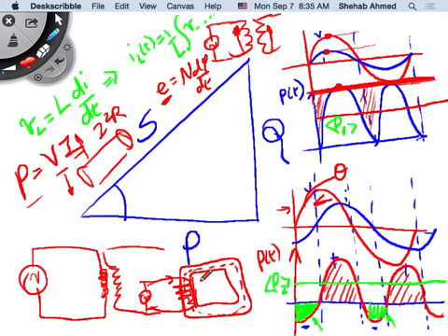Okay? So this voltage, where does it appear? This voltage appears here on the transformer's winding, right? That's why if this voltage appears and you have a voltage here at the input, then the current that's flowing is equal to what? Superposition. This voltage minus this voltage divided by the impedance of the circuit, right? So it will be some value of current.